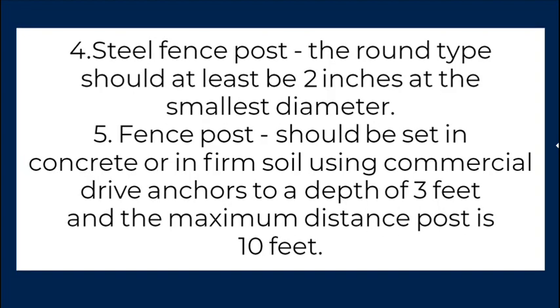Steel fence post, the round type should be at least 2 inches at the smallest diameter. 5. Fence post should be set in concrete or in firm soil using commercial drive anchors to a depth of 3 feet, and the maximum distance between posts is 10 feet.